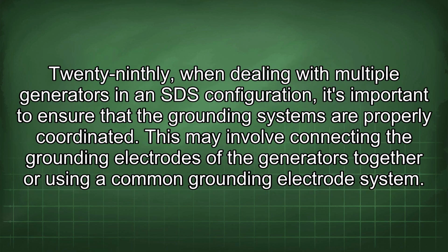29thly, when dealing with multiple generators in an SDS configuration, it's important to ensure that the grounding systems are properly coordinated. This may involve connecting the grounding electrodes of the generators together or using a common grounding electrode system.